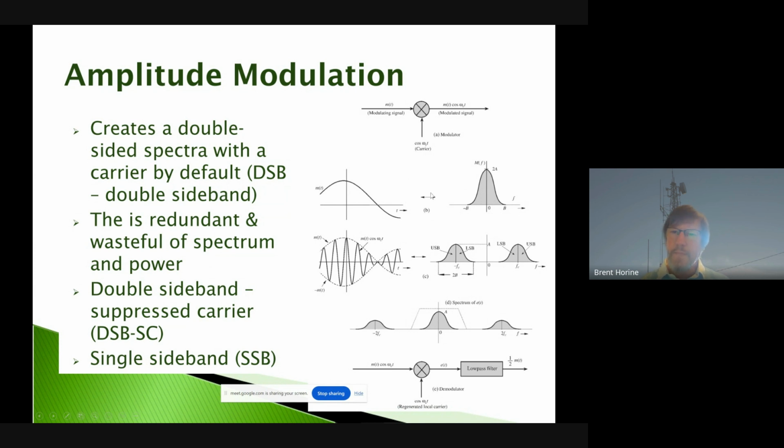So this information here in the negative frequency region, which ends up being the lower sideband, is redundant, right? We could choose to look at just the lower sideband or just the upper sideband and be able to reconstruct our signal, knowing that it's a Hermitian type of signal.